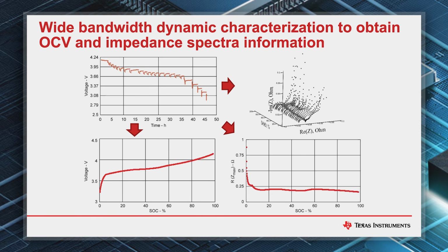So the impedance spectra is highly dependent on state of charge, but you can also see that the high frequency, which is on the left side of this impedance spectra, actually changes little. And that is why we can use this for things like temperature correlation, for example, or even for some things that change little with state of health. But with the aging, the low frequency of this impedance will also change, and that is why we need to keep updating it constantly in the system.